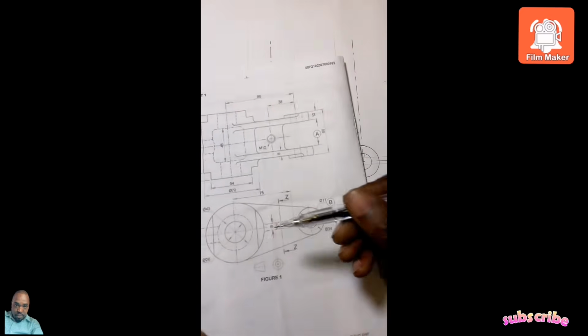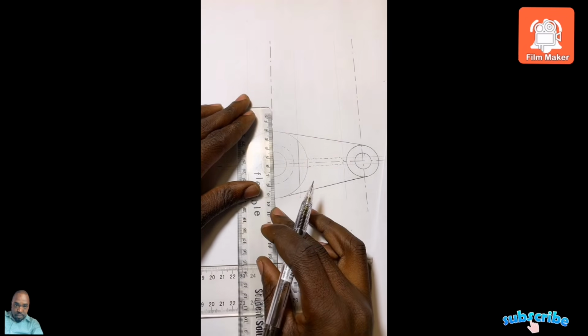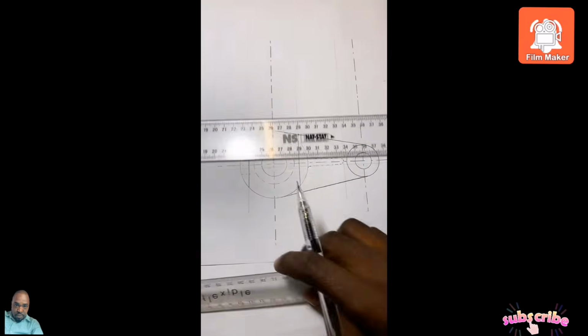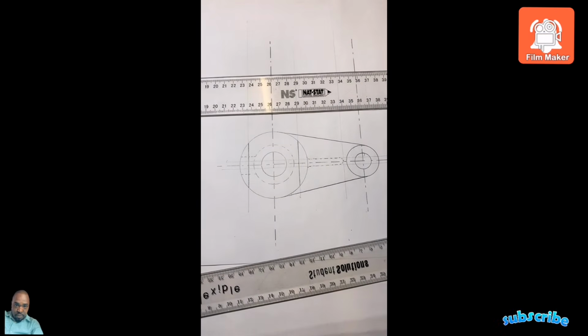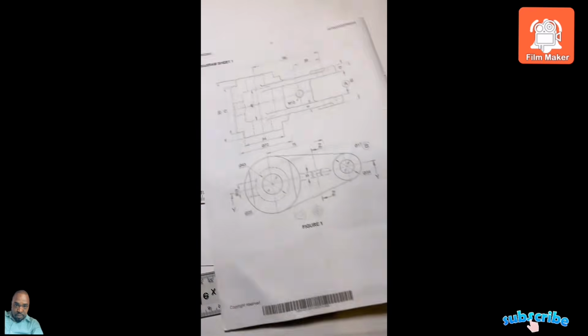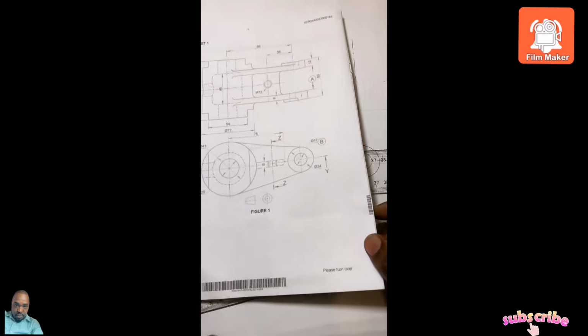So now I'm going to approach to draw the front view. So I'm going to observe the orthographic projection law, which says separate your views with 20 millimeter. So I'm going to have a faint line horizontally. You see, draw it further so that it's also helping you there by your left view. We do not talk about the word right, since this is the projection symbol of the first angle orthographic projection.